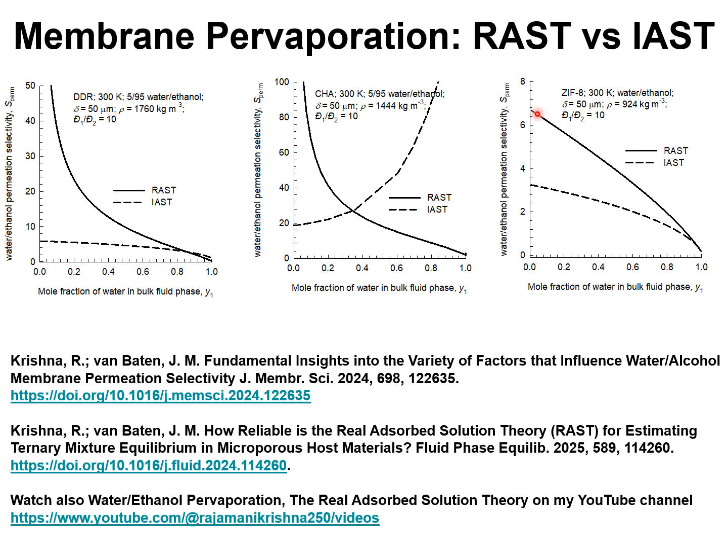For ZIF, the RAST calculations are about a factor 2 higher than the calculations based on the IAST for mixture adsorption equilibrium between the upstream compartment and the upstream face of the membrane layer. The details of these calculations are provided in my Journal of Membrane Science paper.